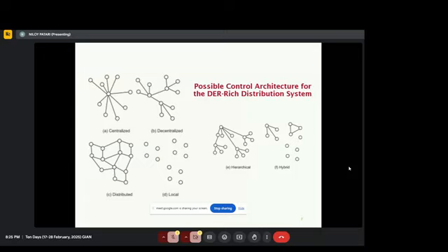That unit will take the 10 measurements, or whatever measurements it is getting from the 10 agents. It takes those measurements in and does certain computations. It can be optimization, control, whatever it is. After computation, suppose it says that the tap setting of this regulator should be this much, this capacitor should be on, this capacitor should be off. So they will send those set points back to those agents, right?